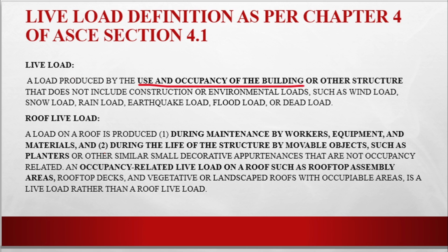This is important: you will select the live load on the basis of the intended function or intended use of a structure, and it does not include construction or environmental loads such as wind loads, snow loads, rain loads, earthquake loads, and many others.